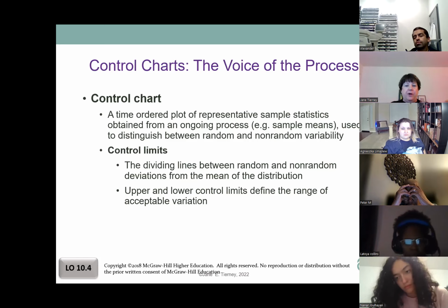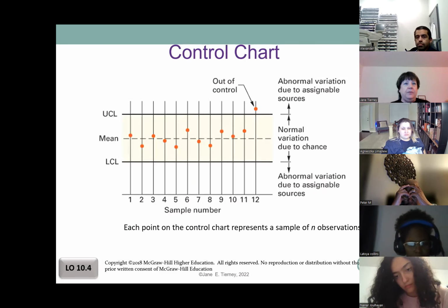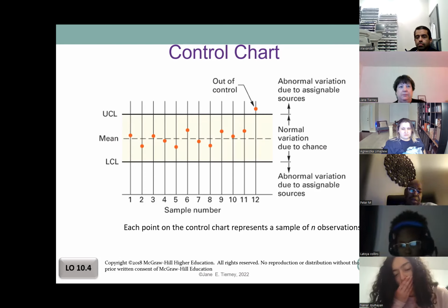And if we have a process that's in control, then our control limits are going to be inside our spec limits, and we're going to be able to keep working. In this case, this is a similar chart to what we've seen before. We're going to calculate the control limits, and then we're going to keep measuring and keep plotting.